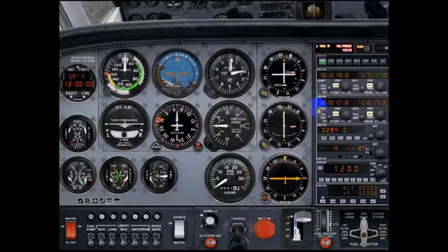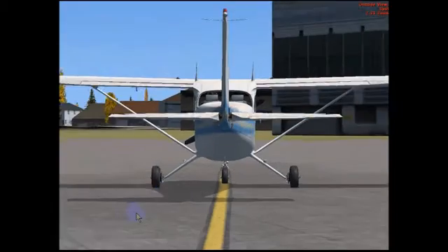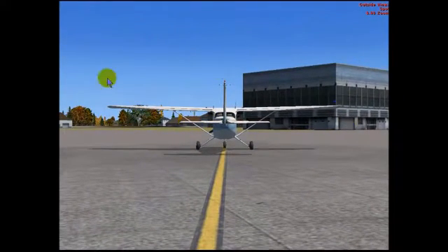And what we commonly do is we turn our rotating beacon on. When we turn our rotating beacon on, what this does is signal to anybody walking around our aircraft, pilots and ground crew, that, hey, my engine is about to start. So that is the purpose of that. When you see the red rotating beacon or the red light flashing, stay away from the engine.